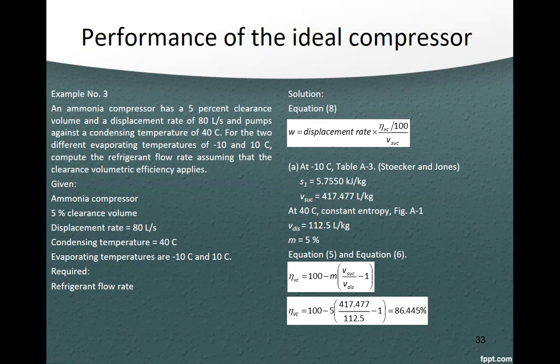Required: refrigerant flow rate. Solution: from equation 8, W is equal to displacement rate times volumetric efficiency over 100 times the suction specific volume. That is the formula.